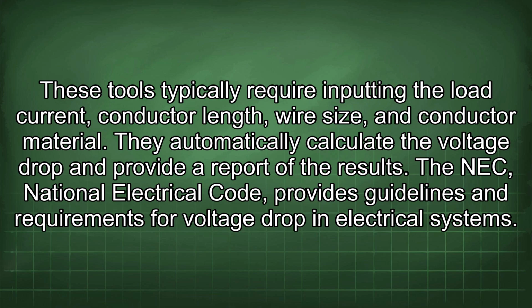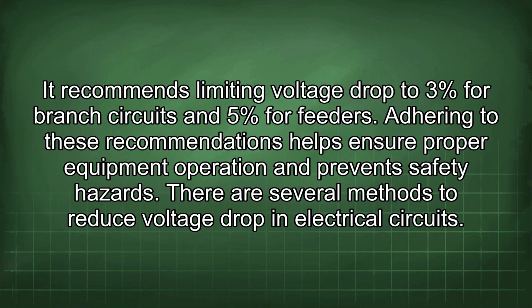The NEC, National Electrical Code, provides guidelines and requirements for voltage drop in electrical systems. It recommends limiting voltage drop to 3% for branch circuits and 5% for feeders.